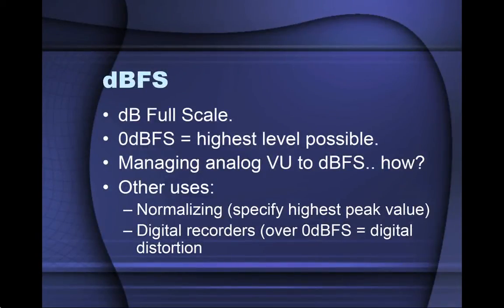Now, if there wasn't enough confusion, dBFS will really make your head explode, because dB full scale, which is used in almost all digital devices, represents the maximum input recording level or maximum signal level that the device can handle.